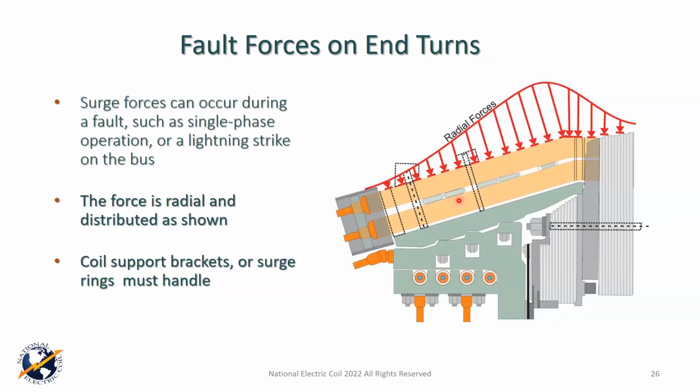So resonance is a function of its natural frequency, just like a tuning fork. And the vibration can be caused by a number of different things. It can be vibration in the frame, the foundation, the rotor itself transmitting into the machine. There are all kinds of reasons you could have vibration, which you could see with dusting or greasing. But resonance is an exceptional condition, and it's the propensity of that assembly to vibrate more at one given frequency than any other, and that given frequency is its natural frequency. Okay, so Franco, I hope that helps you a little bit.